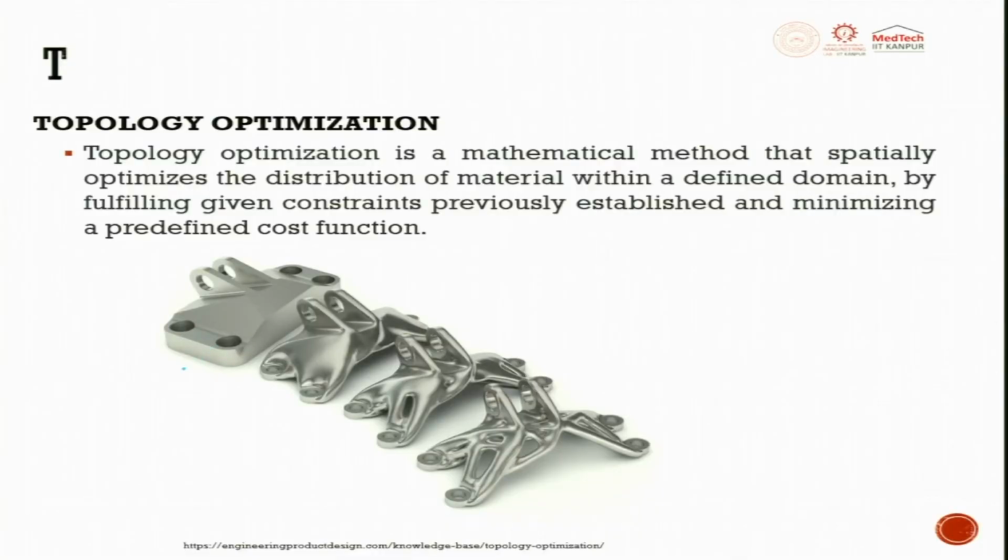Topology optimization: you see this object finally is converted into this object by doing topology optimization with respect to shape, size and pores. So, a solid block, and this is where today additive manufacturing is preferred. Convert the solid body product which is made out of a subtractive process in this way, keeping design for manufacturing and assembly into account. Now you look at these objects, and when you do topology optimization, you see the amount of reduction, and this entire thing is a single part.